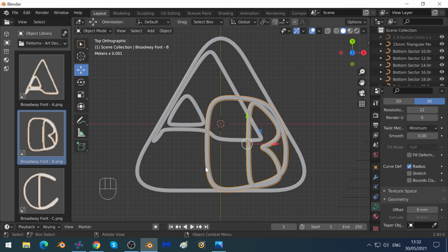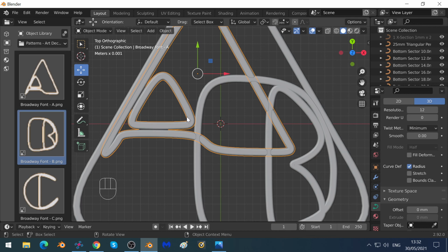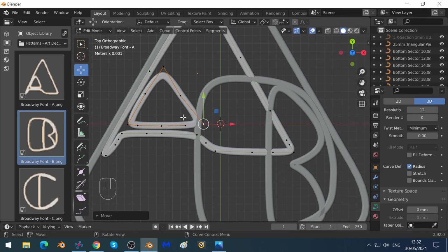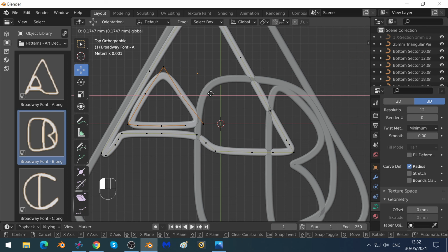Now, it's very important that there are no objects that are not touching something else. Now I can see that this triangle here, if I zoom in, is probably not clearly touching somewhere else. Well, I can fix that quite easily. If I go to edit mode, click on that point there, click on move and then drag the red to the right, I can just overlap, and I'll also click on that point there just to make my triangle more of a triangle again.